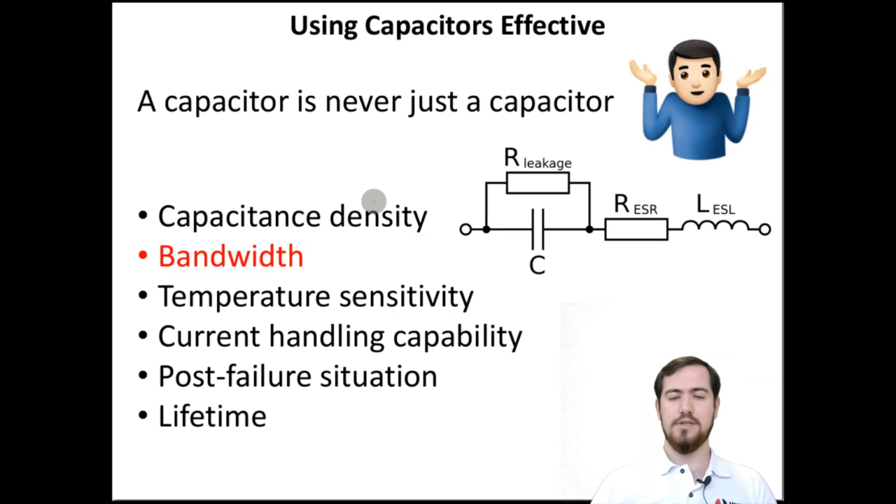As I just explained before, the effective usage of capacitors is a very important concept because these capacitances are not ideal. I mean, for a high frequency application, we cannot use an aluminum electrolytic capacitor because it has a very large amount of parasitic inductance.